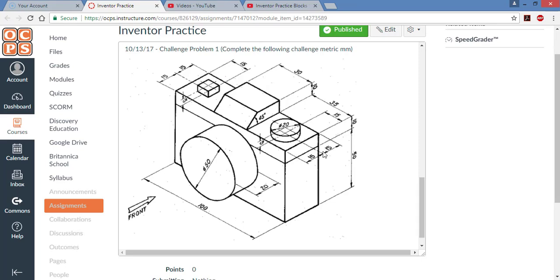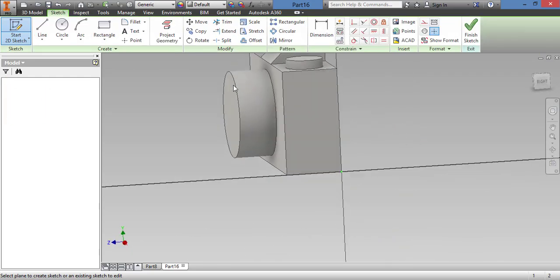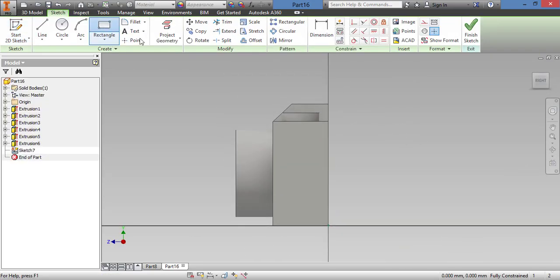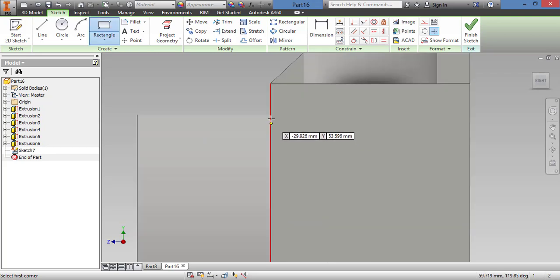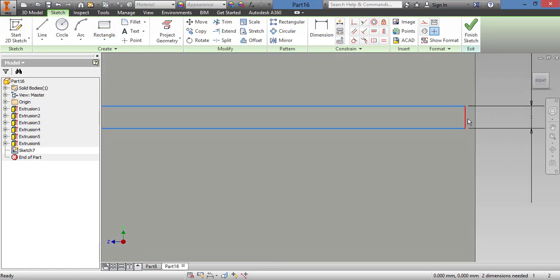If you are feeling comfortable with it, and I do suggest that you try it if you have enough time, you can start a sketch and go ahead and create the new sketch, and then what I would do is I would just find a spot and make a rectangle. It doesn't really matter how big. I'm going to go ahead and give this one a thickness of 1 millimeter. And since I already left clicked, I'm going to click here and drag this over to the edge.